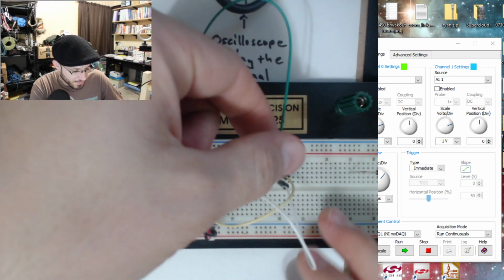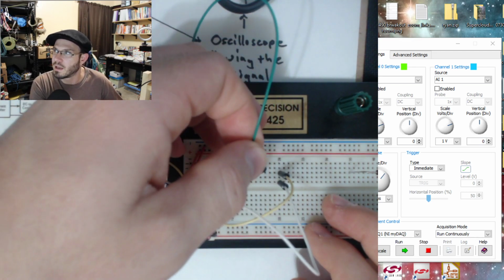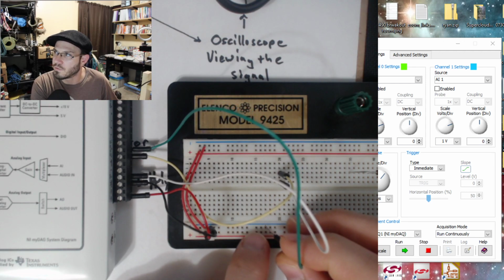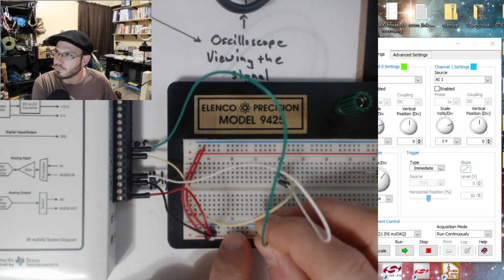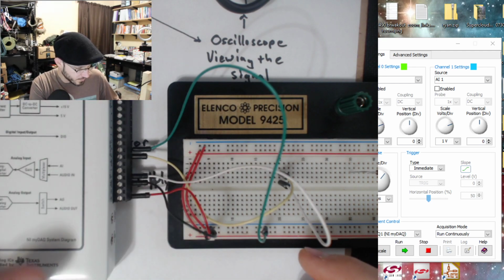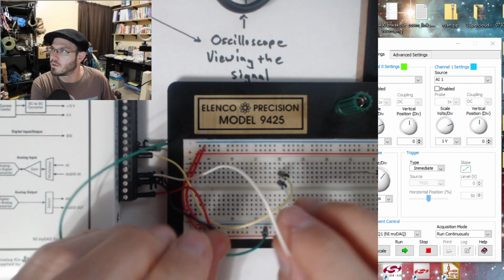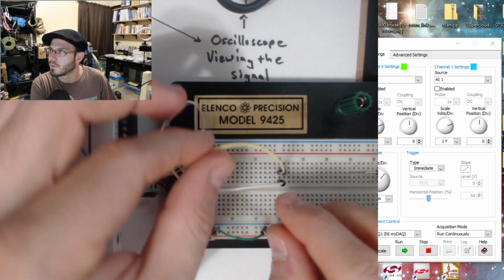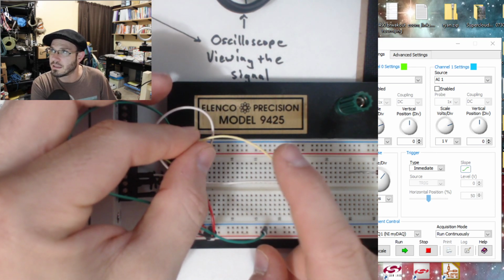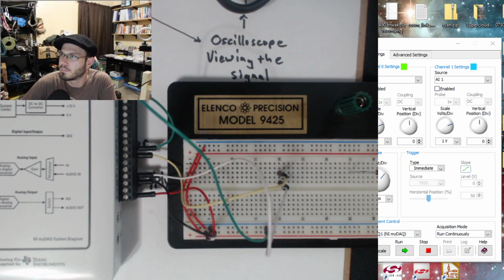Now green, remember I have to measure a voltage with respect to something. So I'm going to connect this to ground since that's the 0 volt reference for all of our circuits. And ground is going back to the MyDAQ through this black wire. Okay? So now hopefully if you can see, I have the function generator output connected to the oscilloscope input. Now let me go ahead and switch back over.